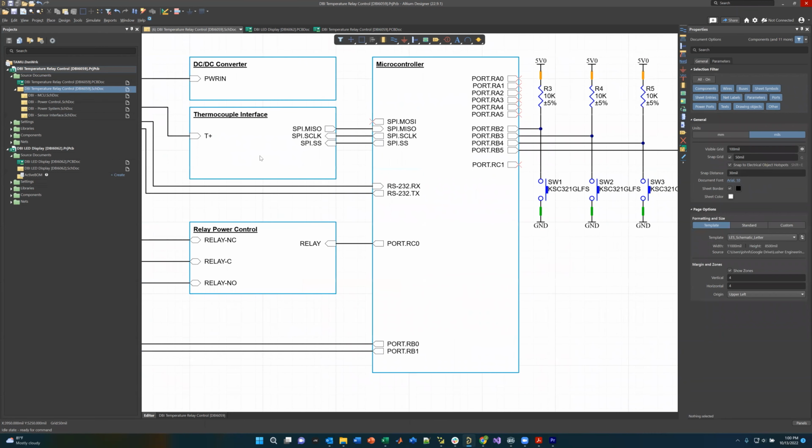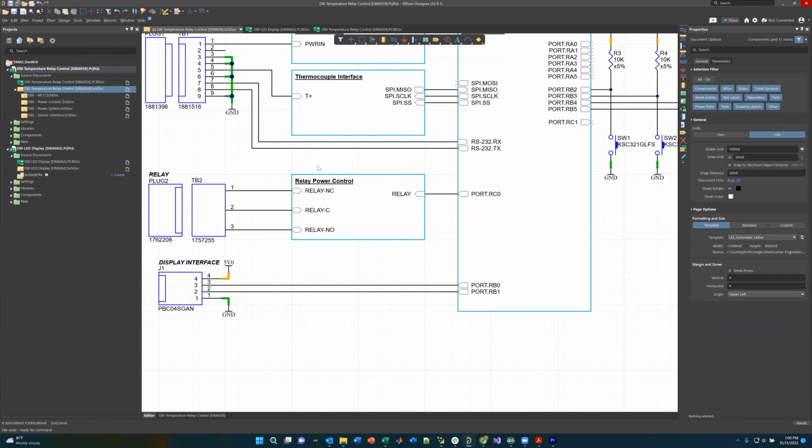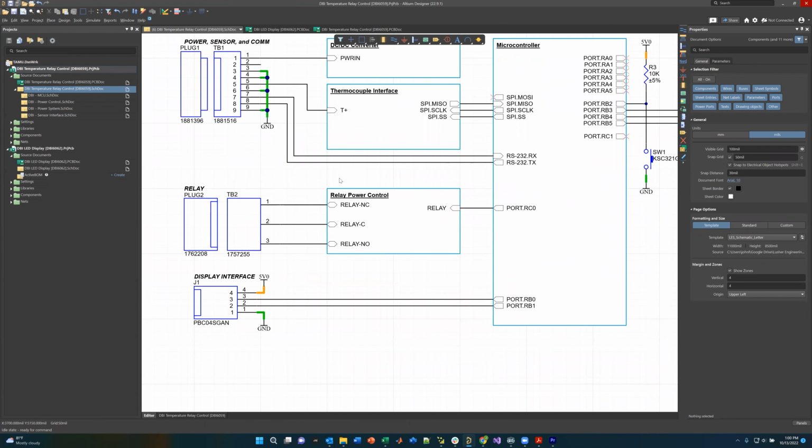All right, so moving on here, we have a relay. We'll cover the microcontroller later. So we have the relay. A relay is basically a remote controlled switch. Think of it as controlled by a solenoid coil. This is supposed to be a 10 amp relay that's going to switch whatever voltage the client wants, up to 240 volts AC, through the switch. So we have a normally closed and a common contact. With no power at all, when this board is unpowered and there's no power going through the relay, this is shorted to this contact. These two pins are shorted together.